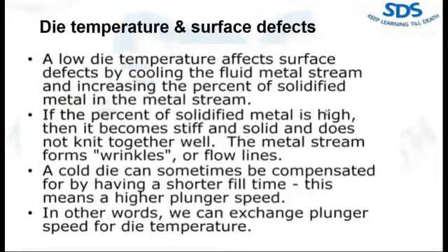For example, if we require 0.03 second filling time, and we increase the percentage of solid, we are not able to maintain this filling time. We will get some 0.04 or 0.05. So we'll create or generate this surface defect, right?